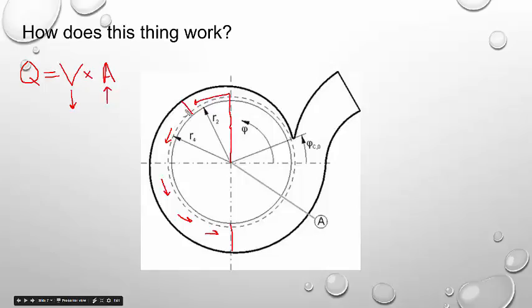The width versus this now, this is almost double the width down here. So my area has effectively increased 2 times. And by the time that I exit the volute, I have a fair amount of area that I'm working with. So if this number is really big, that means this number has to go down. And if the velocity is down, I have efficient energy transfer.